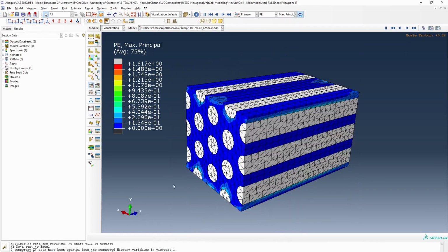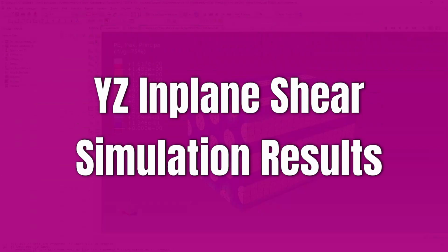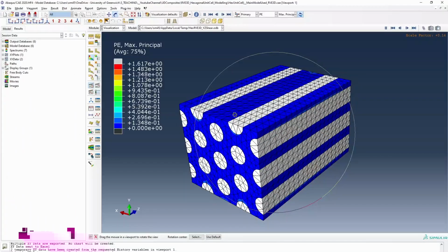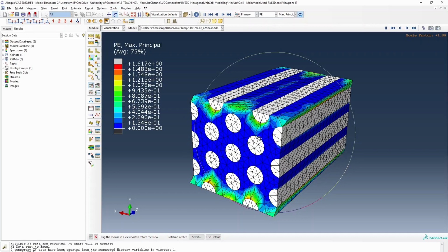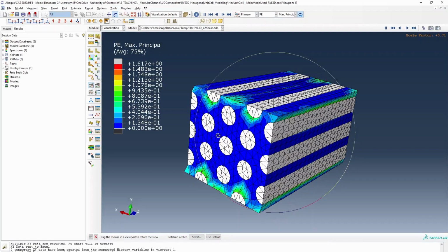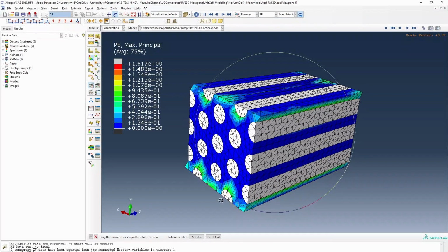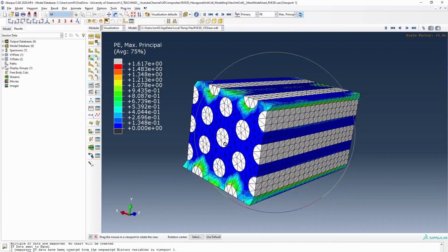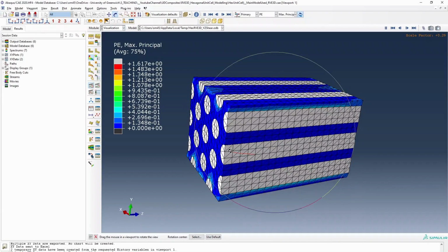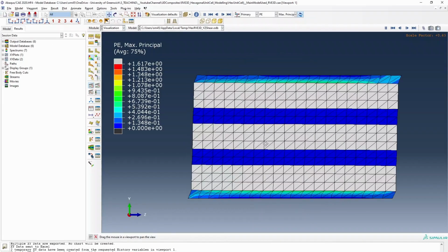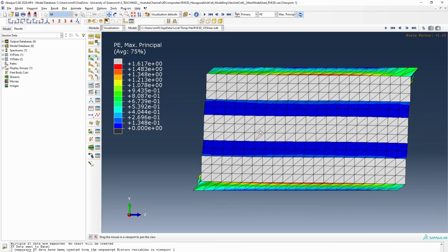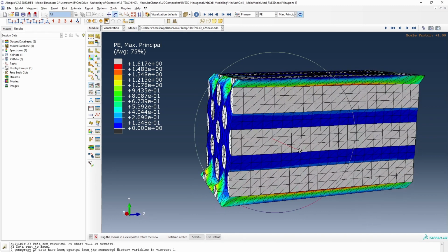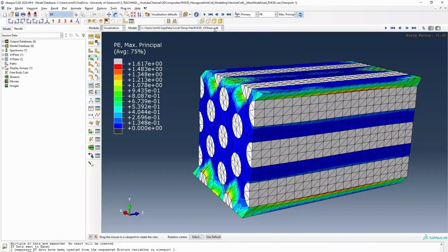This case shows us the YZ shear. So you're pulling it in the Z direction on the plane where the outward normal is the Y. So you can see what's going on again. You're shearing along the fiber axis, and you're getting some interesting results from this. We can also look at the YZ plane. It shows the deformation on the YZ plane with the fibers remaining almost intact, exactly the way they are supposed to be. So the last kind of shear is the ZX-Shear.